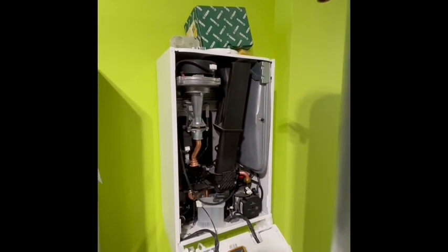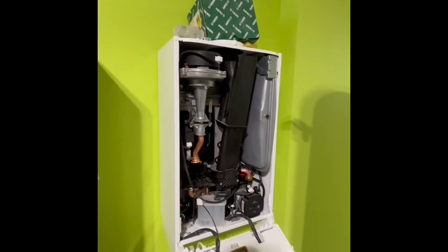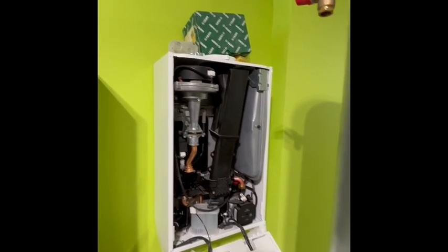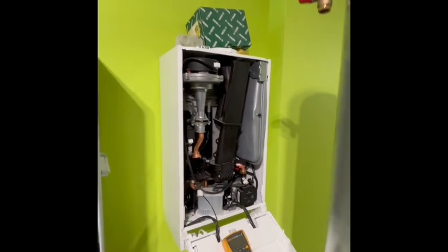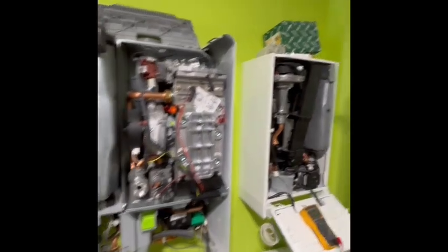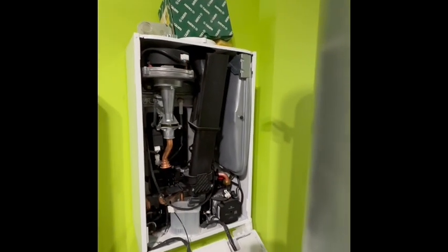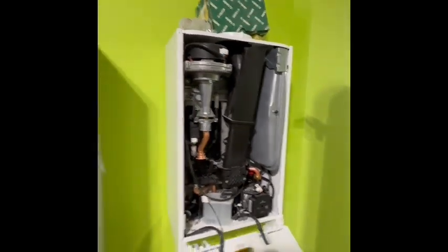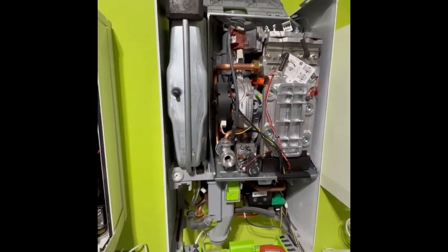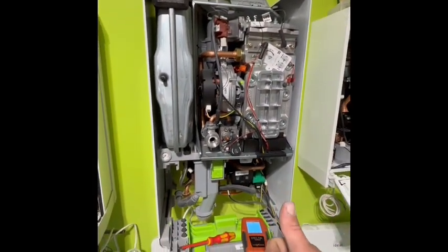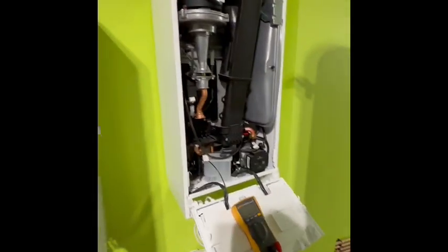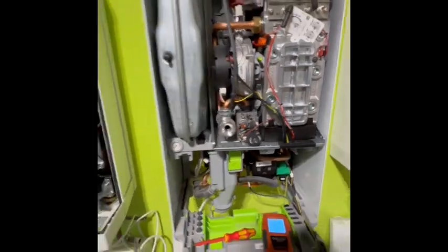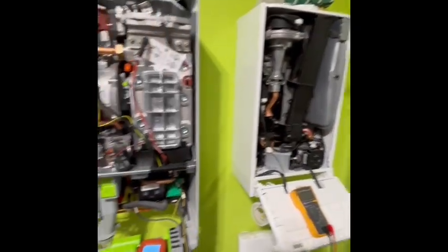So if you remember, you need 3 components for combustion. If you start restricting that air, then it starts becoming noisy. When it starts becoming noisy, you can have an unstable burner and it's restricting it, so it'll just blow it off the detection electrodes, and then it'll give you, on this particular boiler, an L2 fault. So it's always down to those 3 things. Have we got gas? Have we got ignition? Have we got oxygen? And the ignition, the condensed backing up, is oxygen related. Although everybody thinks it's just water in there, it's actually starving it of oxygen.